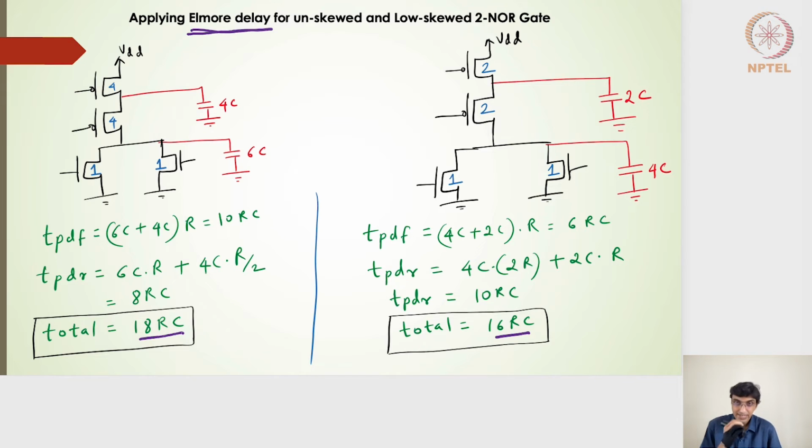So that's what we had noticed in the previous slide when we calculated the logical effort, right? So logical effort, although it will be used for the next stage, what it says overall is that particular stage has less delay. So if I want to find out the best sizes, so that my total delay, in the sense the propagation delay falling plus the propagation delay rising, the sum of it should be less. If that is the case, I need to identify the best size.